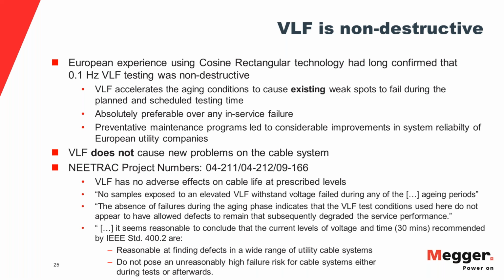And the step test is really bringing the insulation to its limits to see what the actual remainder of the breakdown strength, remainder of the life actually is. So the intention of the step test is to fail the sample. The intention of the VLF test, or the withstand test, I should say, is not to fail the cable.